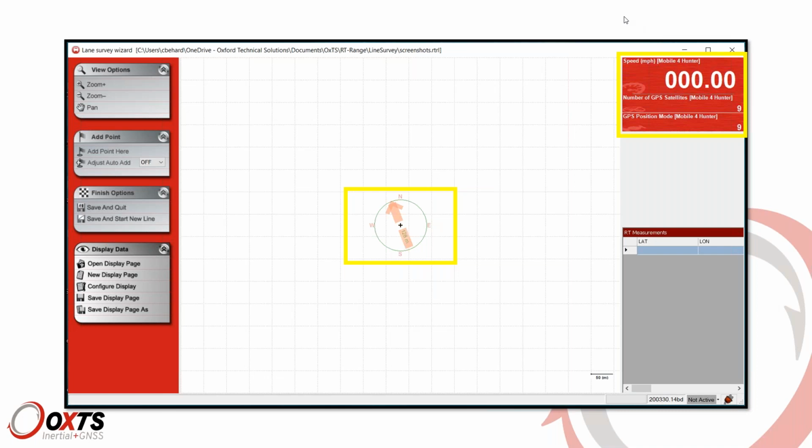So this software simply takes the position and heading of the RT, and you push the survey trolley to the start of the line, and then you can monitor the RT's position and heading, but also its accuracy in some measurements in the top right-hand corner, which are labeled here.